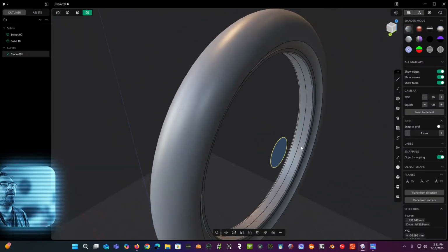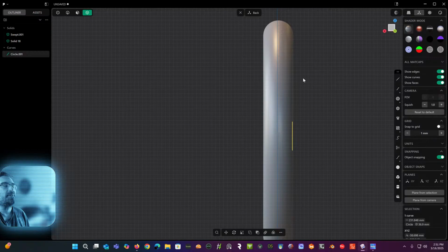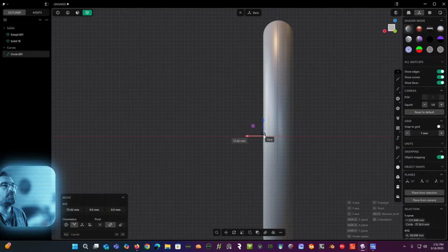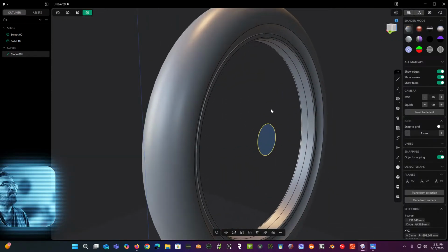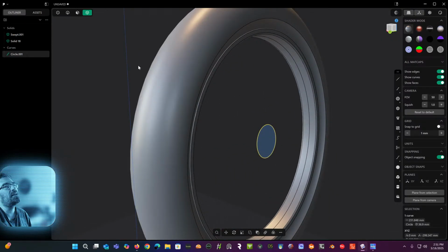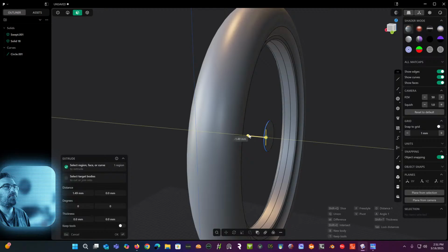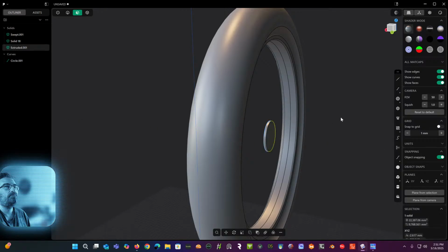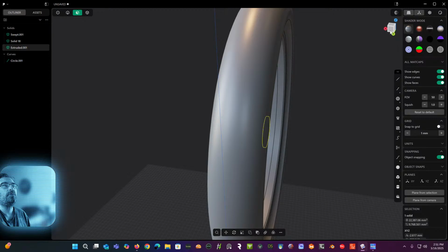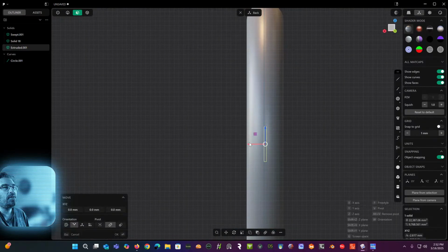And we're going to center that from the side here. I'm just going to grab it, Control Shift till it snaps. If it doesn't, I have to go over here, which works the same way. And because this is going to be a thin part, now that I think about it, I'm probably going to take it and just pull this out slightly like so. I'm going to have to move that out to the width of wherever this was going to wind up going. And it could probably be a little bit out here because we're going to have the spokes coming back in.